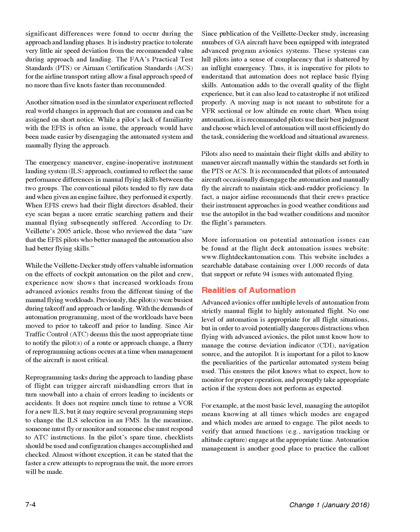It does not require much time to retune a VOR for a new ILS, but it may require several programming steps to change the ILS selection in an FMS. In the meantime, someone must fly or monitor and someone else must respond to ATC instructions. In the pilot's spare time, checklists should be used and configuration changes accomplished and checked. Almost without exception, it can be stated that the faster a crew attempts to reprogram the unit, the more errors will be made.